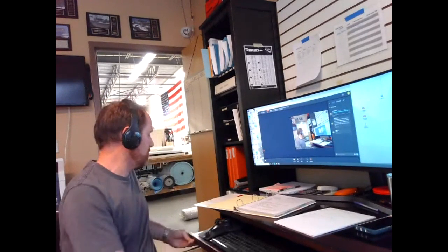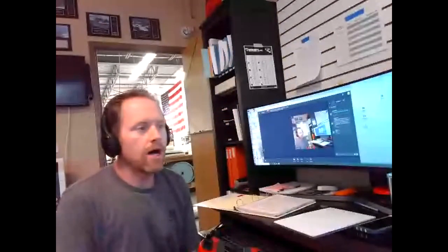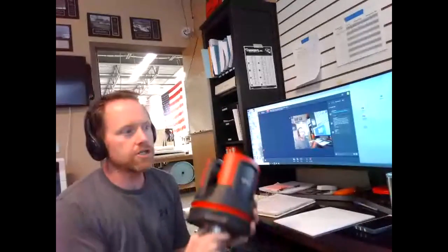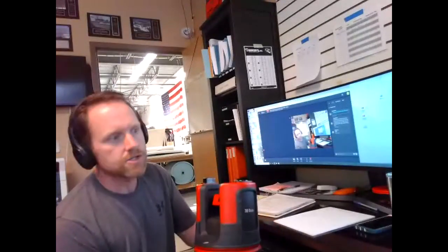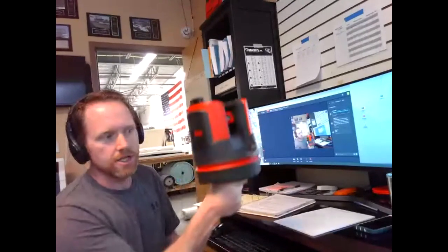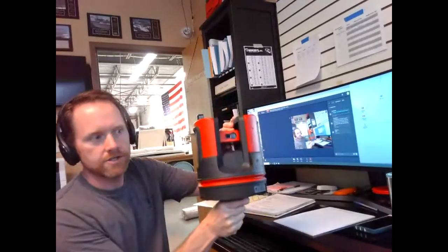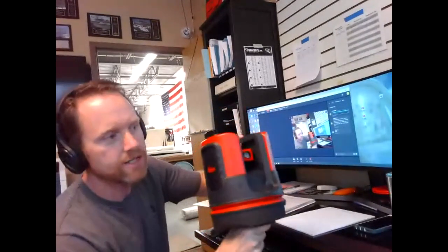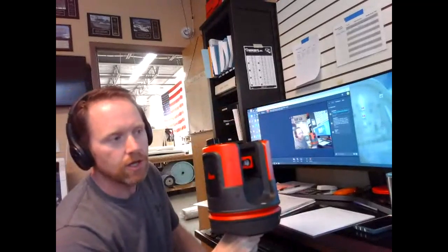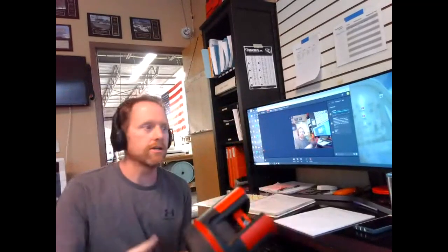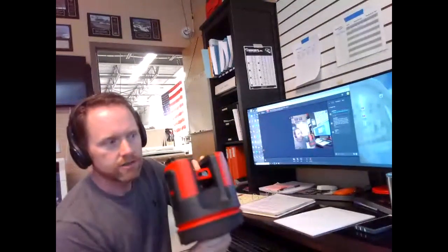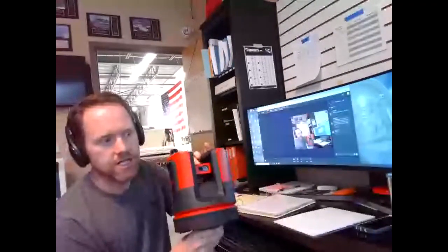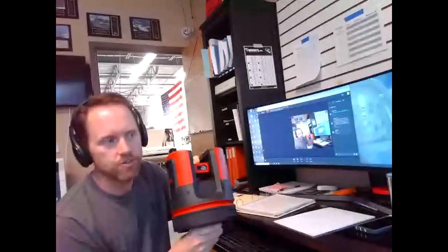Once you do that, just to show you a couple, again, this is going to go quick because we only have about 45 minutes. But one of the first tools that we started using when we started doing 3D is called a laser, just a laser system. And really what this does is it mounts on a tripod. There's a camera here that you can either move by hand, and it has a red dot that would point at the location where you want to take the measurement. And then using a tablet, you would just click on the tablet to take the measurement. This also has a camera in it, so on the tablet, you could see what you were trying to focus in or zoom in on.